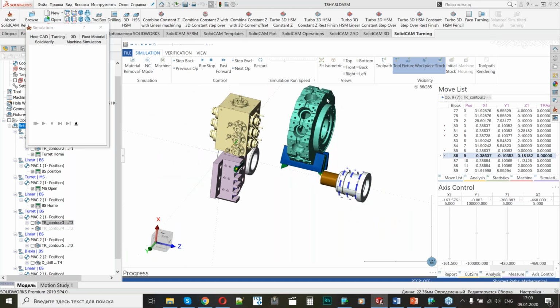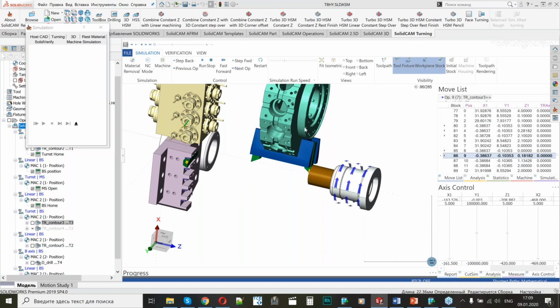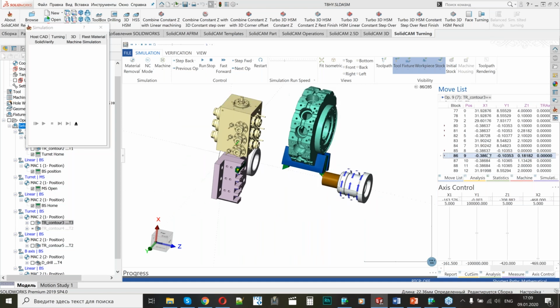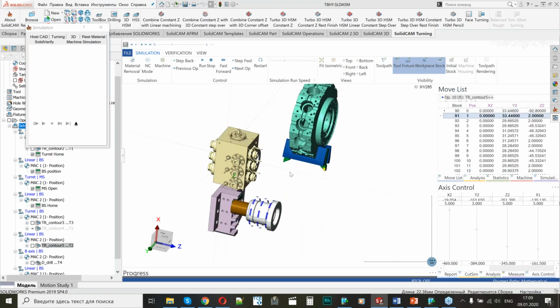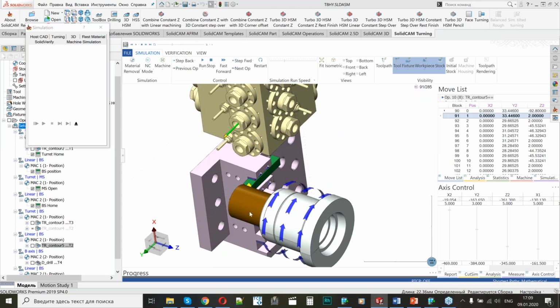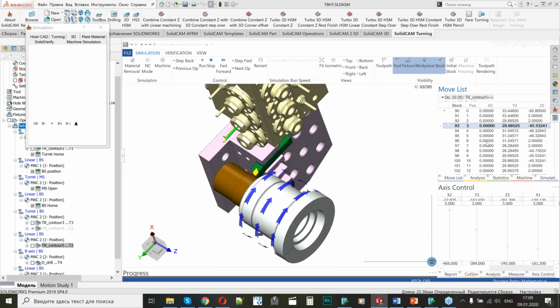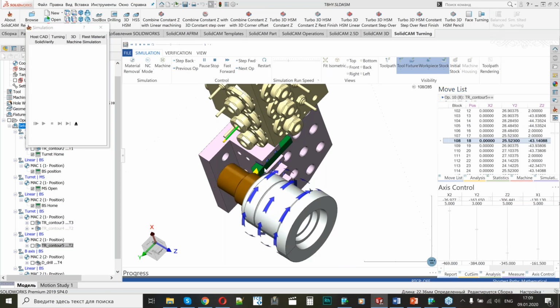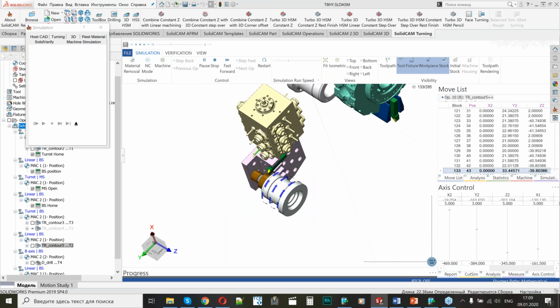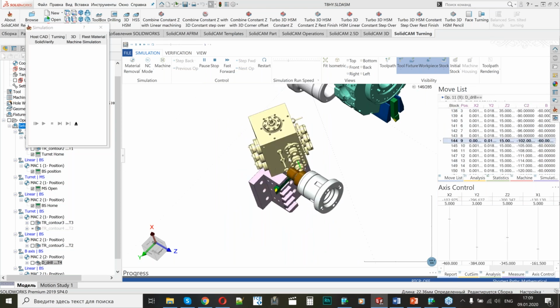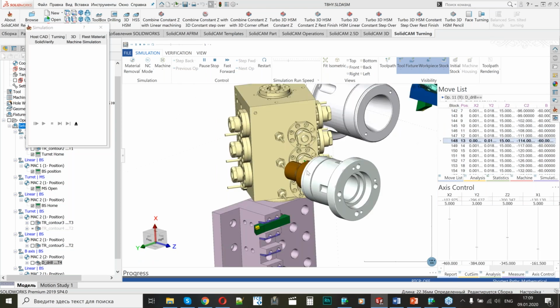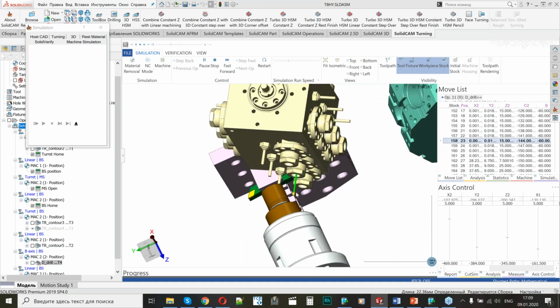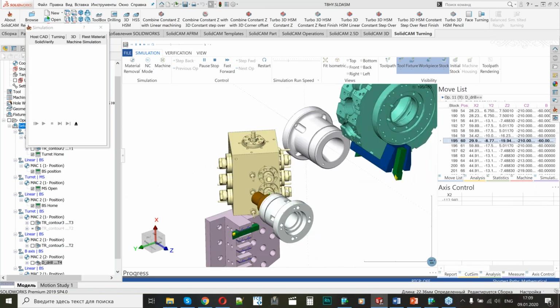The second submachine will be the combination of the rotary turret and the back spindle. And after that, I can provide operations with the linear turret and back spindle. And then the milling operations, only milling operations, with my B-axis turret and the back spindle. So I will have to create 4 submachines which should support all these types of operations.